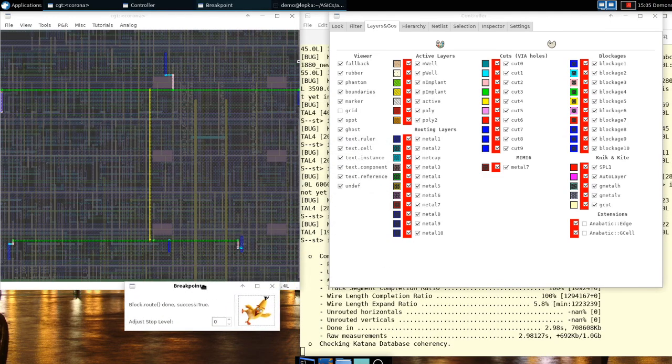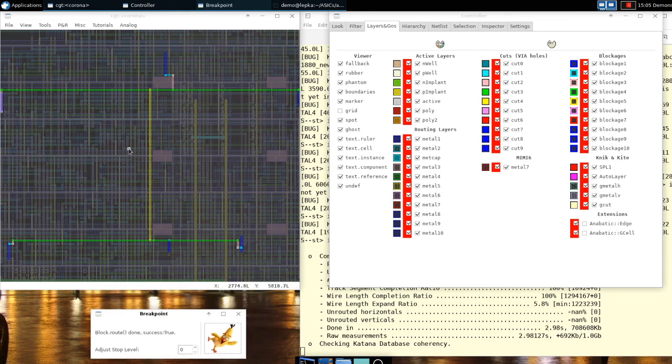Okay, here we go. So now the net is fully routed, and you see that the routing has succeeded, as the little window says to you. So you see that it has moved some of the wire into the metal 4 and metal 5, because the edges were overloaded or highly loaded, so the router estimated that it was better to go up.